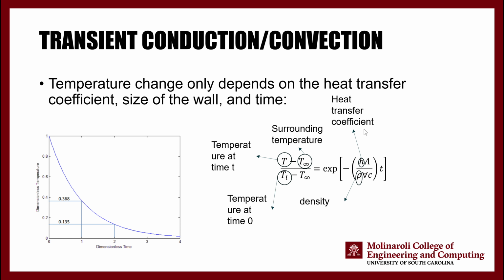Your goal in the second experiment is to measure the temperature change over time of a copper block and then to calculate the heat transfer coefficient. Area is the area of your copper block, your solid medium, whatever that is. Volume, t is the time that has passed. This is the heat capacity of your sphere in the example, and this is the volume of the sphere.